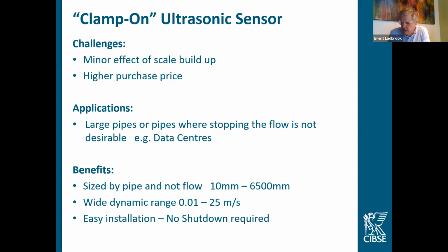The good thing is no shutdown required. So if the pipe is existing and the application is in a hospital or somewhere like that where you do not want interruption to any flows, then nobody inside the hospital would even know that this was happening. You could be in the plant room installing this, no disturbance whatsoever for this type of meter. And excellent diagnostics, probably the best diagnostics are in clamp-on ultrasonics. But they kind of need to be as well to prove that they're working correctly.